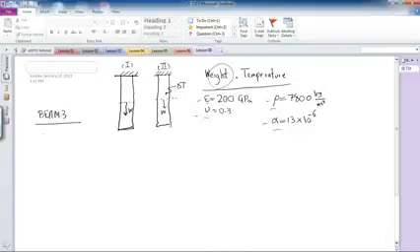And if you remember from previous examples, for Beam 3 I have to give a real constant, for which it asks me for cross-section area, area moment of inertia, and also some height.